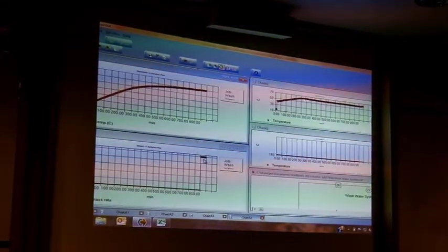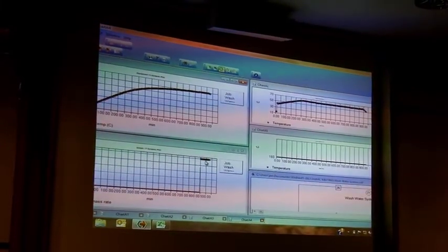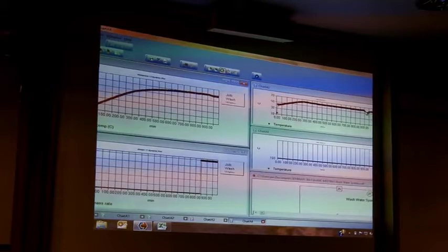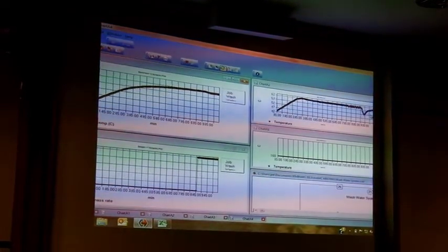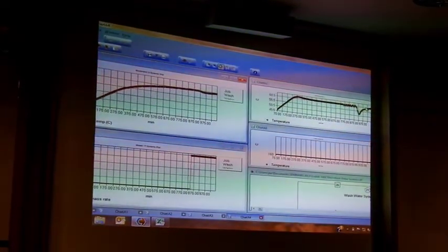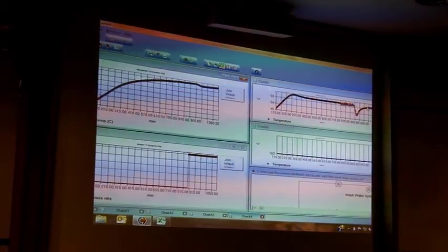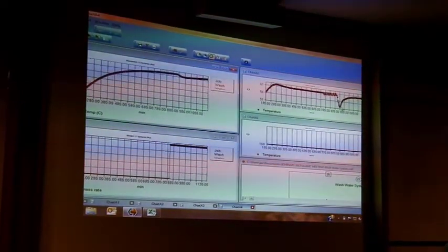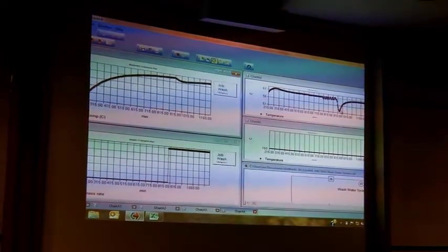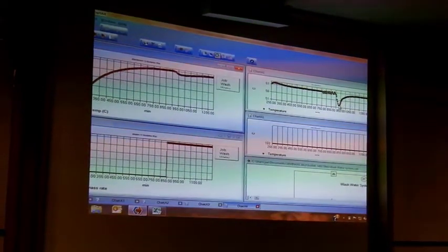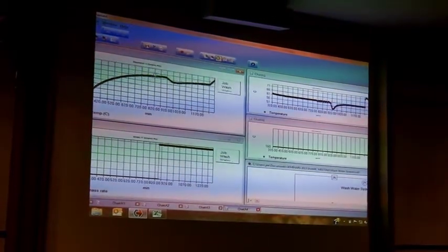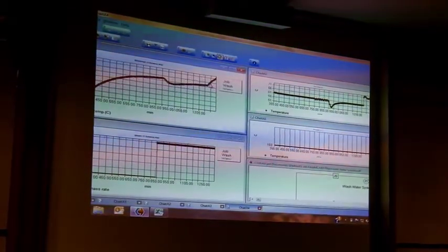Now the water demand has gone on. That's the water demand from plant now at 10,000. You can see it's kicked that a little bit. There's also level control going on here as well, which I'm not showing you, but there's cold water going into the loop as well. That's what's happened here. The level's gone down and we're injecting cold water. That's why it's gone down. But it's not had any effect on the tank here.